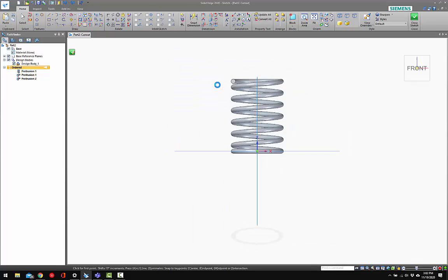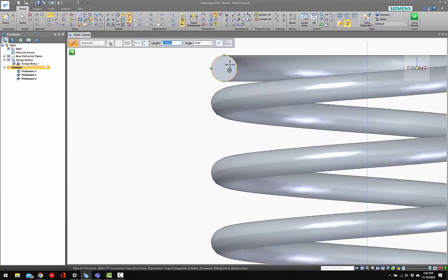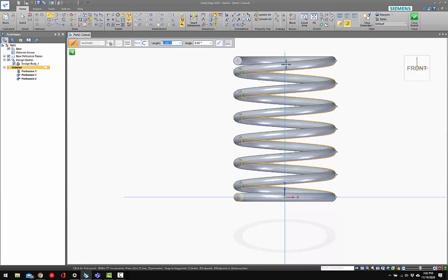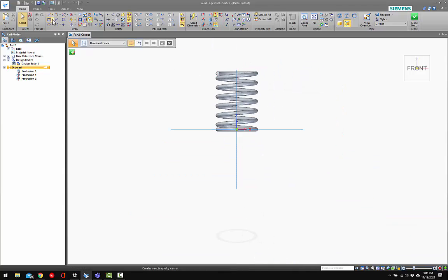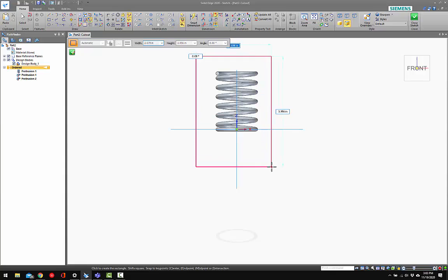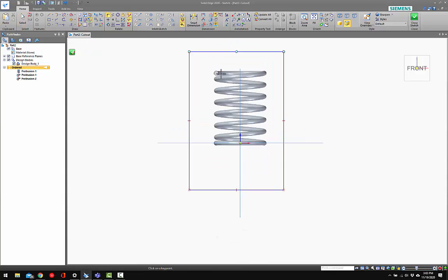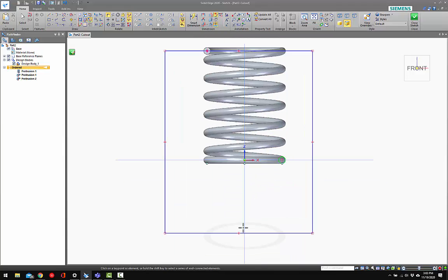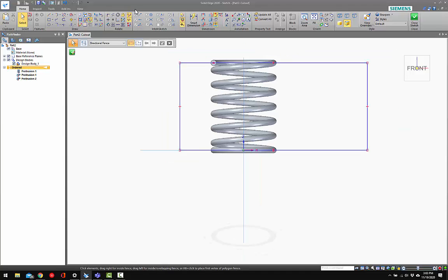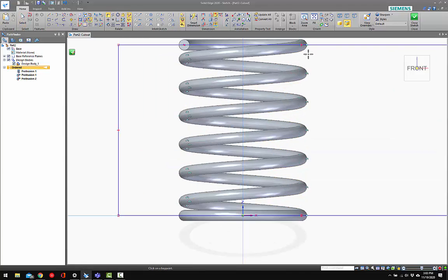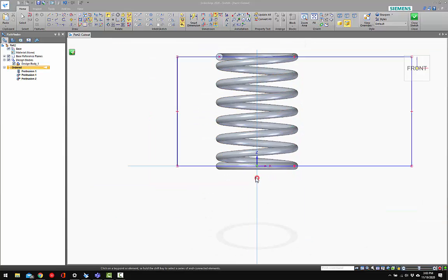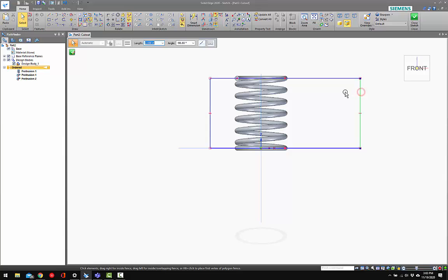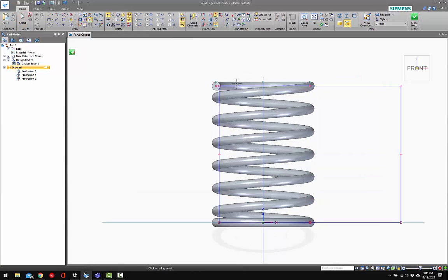All right. Now, this is important to remember. The length of this spring is going to be from the center point here to the center point here, if you remember, because that's how tall that line is that I made. So in this cut, I'm going to draw a rectangle, and I want to make the center of that, because that's usually where it's going to be ground to, and I'll go to the center of that. Now, just because I don't like leaving anything unconstrained, this part doesn't matter, but if it'll work with me here. Let's see. All right, maybe.